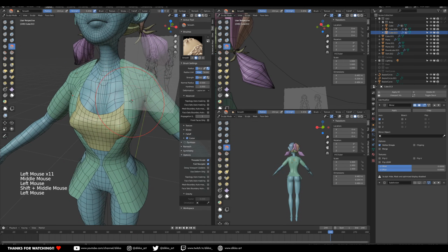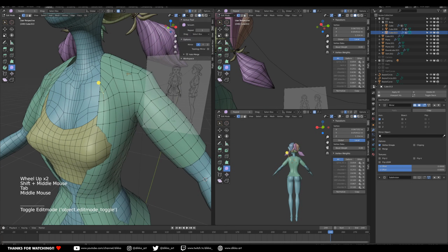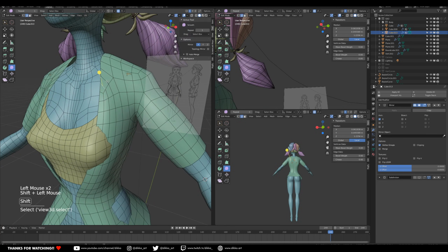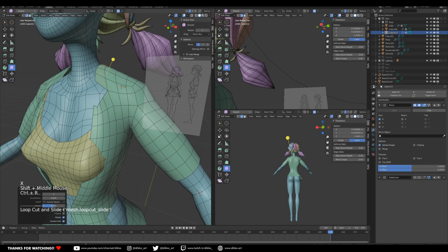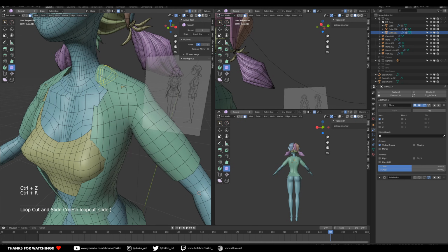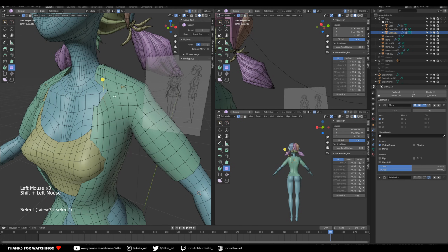And if you haven't noticed already, the edge flow here isn't perfect. Right now, some of the spans are traveling up and then into the side of the shirt. So I need to redirect those to flow around the back of the collar. So that's what I'm doing here. So again, a little bit of problem solving involved, choosing how many spans I want to travel around the back, and then merging the appropriate verts to continue those faces to flow around to the back of the body.